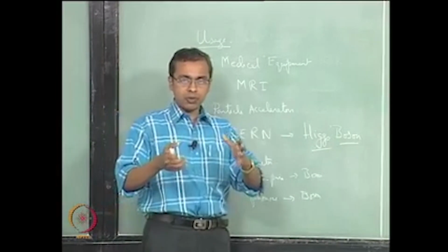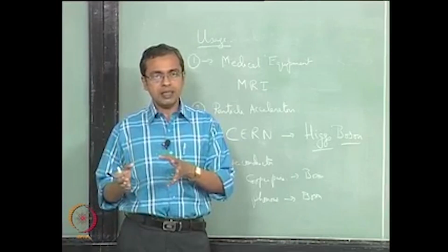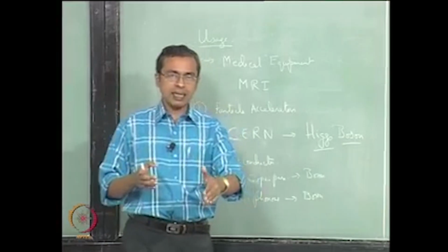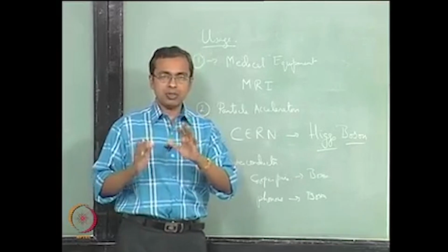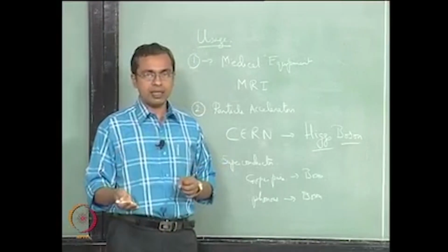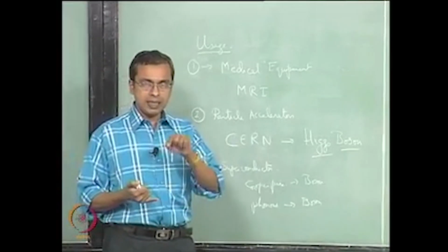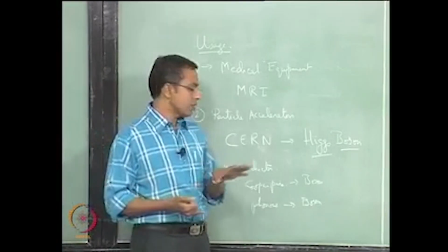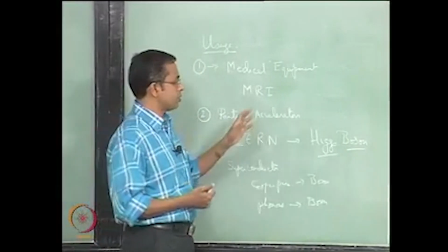It may take several weeks for you to very gradually raise the temperature of the affected system to room temperature, so that you can attend to it, and then very gradually lower the temperature again. Just attaining the temperature and coming back from it to room temperature has to be a very gradual process, otherwise you will create a thermal shock. So this has to be done very carefully. In addition to the fact that it is at low temperature, reaching and maintaining that temperature has to be done in a very controlled way. So even in that sense there is a technological challenge in working with superconducting materials.